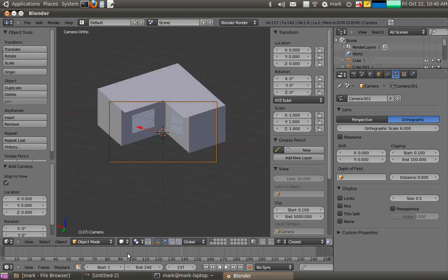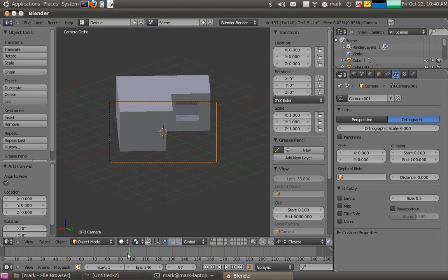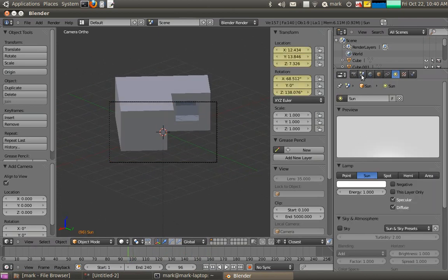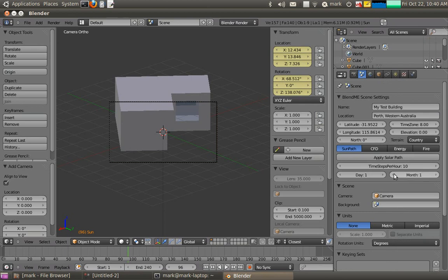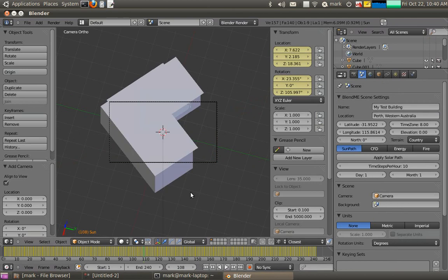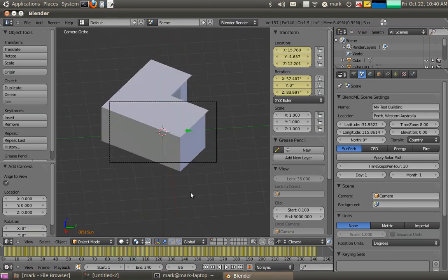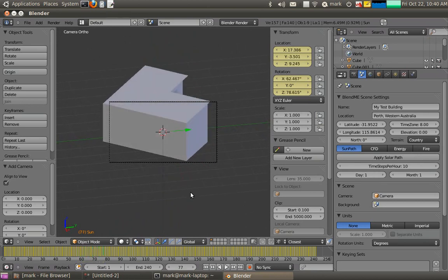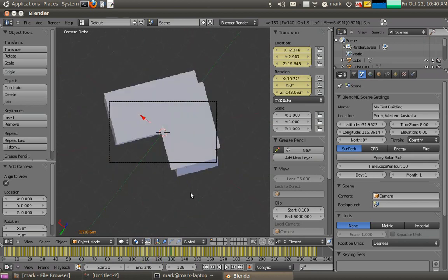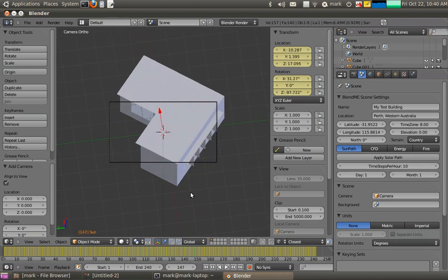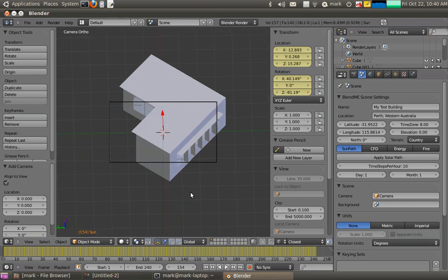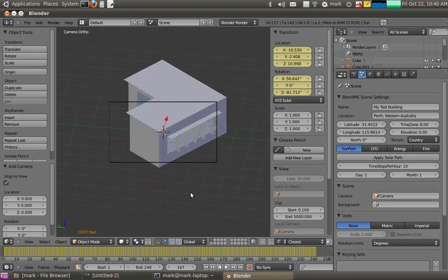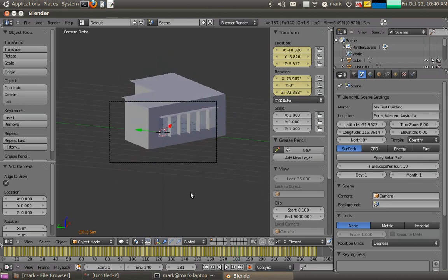Now we might want to see what happens to this in the summer. So we can select the sun, go back to the menu, and I can change this back to the month of January the 1st. And again, we'll calculate the solar path for that. And here, this will be about sunrise. Sun comes up, over. My shading elements are pretty short, so the windows are getting a bit of gain during the middle of the day, because my eaves are quite short. And, oh dear, my southern elements are doing pretty much nothing in the afternoon.